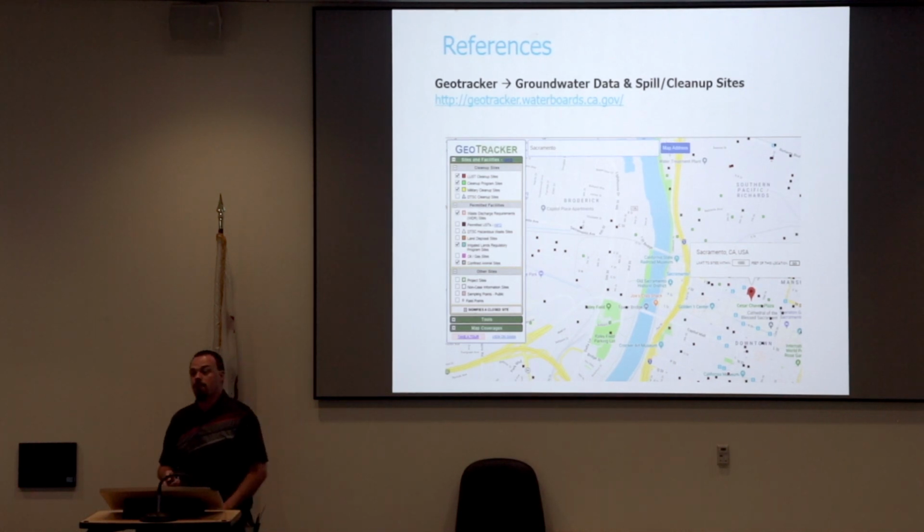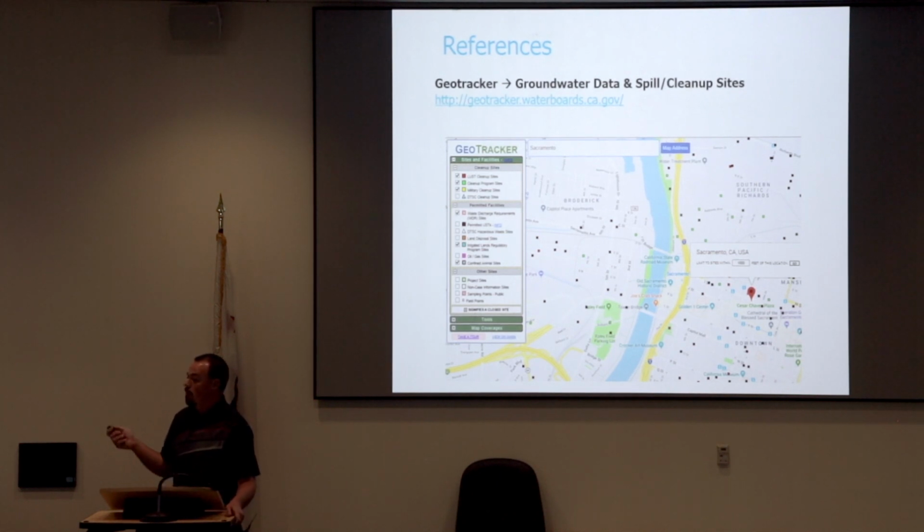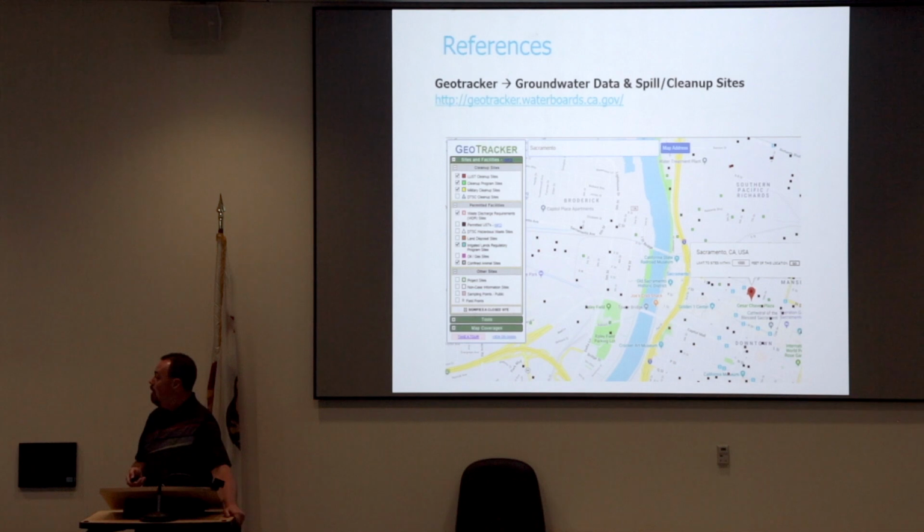Field points. So if you click on field points, anywhere that there's been some groundwater testing in the area, whether it's for a spill on site, you can get groundwater elevation information, historical, from that. You can pull that up and it'll bring up the actual boring logs if they had to do borings for those. So it helps with general ideas of where the groundwater table is without actually doing infiltration testing and individual borings around your site. Obviously not every area is blanketed, but there's usually some generally close wells that you can use for reference.